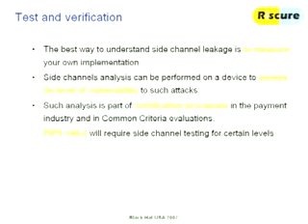The implementation that I had originally for the RSA already didn't have a real SPA. There was a difference between the multiply and the square, but it was only something like 10 microseconds on 400. So you didn't even visually see it. So I had to modify my program and put in a lot of garbage to make a big difference so that you could now see on the screen that there was a square and a multiply.